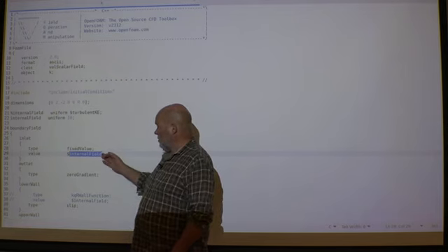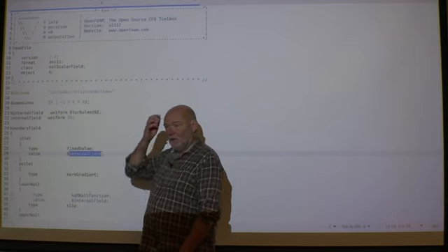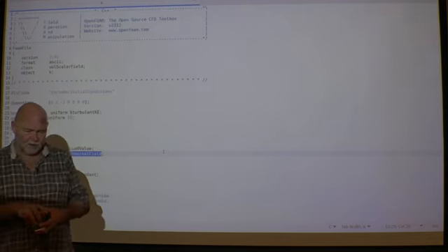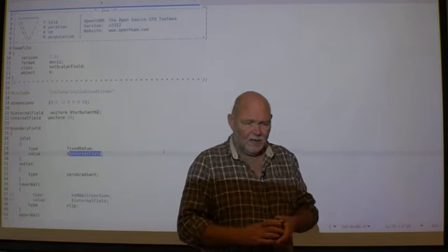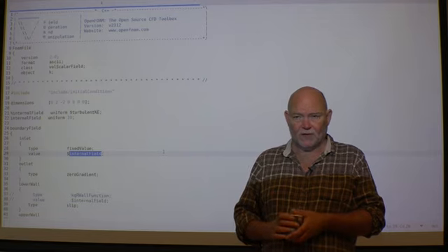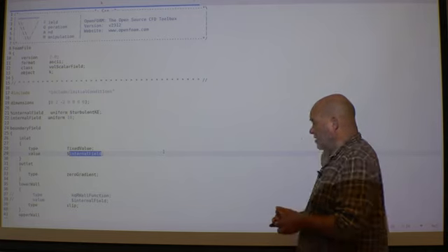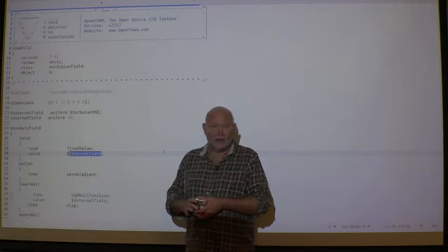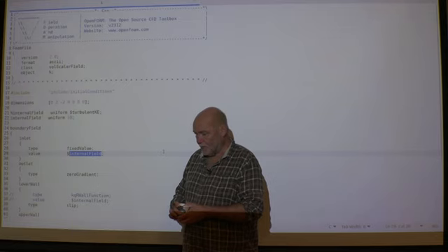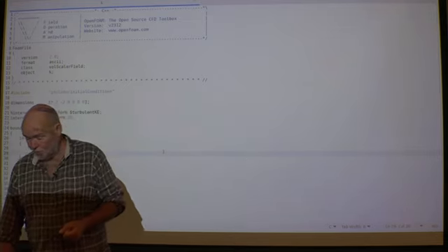I tried it with 3, 30 and 300, and I got hardly any difference at all in the solution. Because for the real simulation, the flow around Donald and his car, of course, the turbulence is going to be created. But the background turbulence intensities should be fairly low. So don't overdo it. Just use a small number. It really doesn't matter how small. So 1 or 10, you will see also, and it should of course be investigated. Will this make any difference, or will it not? And yes, you should see that you don't get much difference in the forces or the drag coefficient that we are seeking.